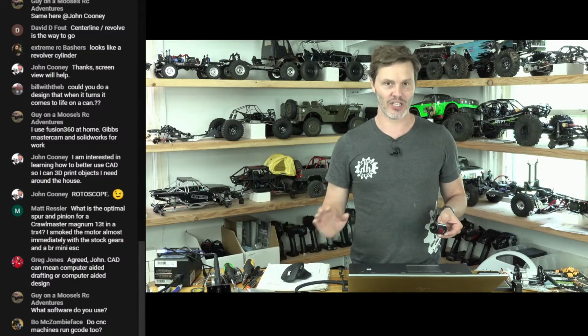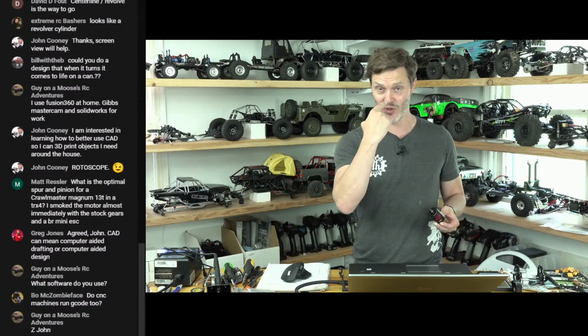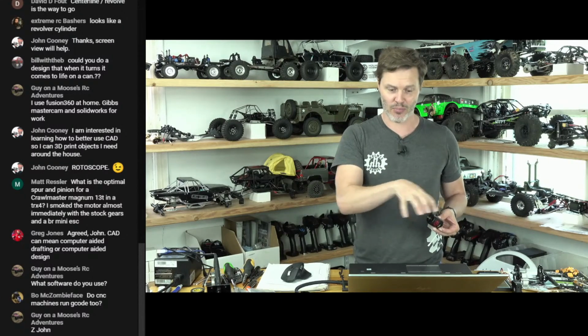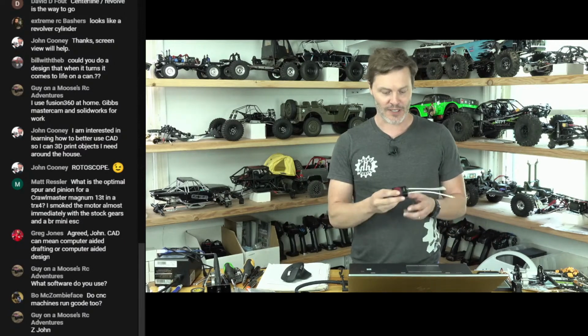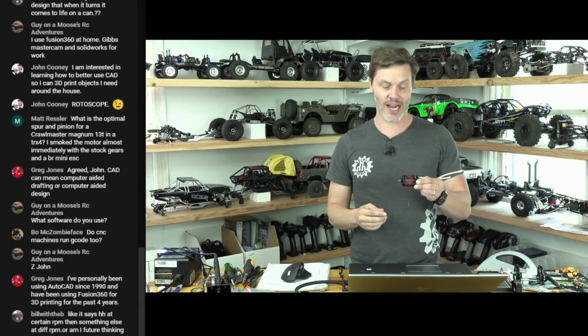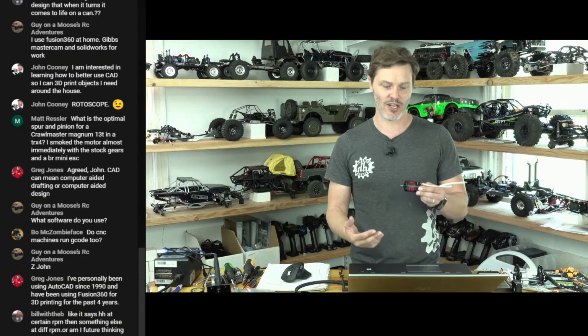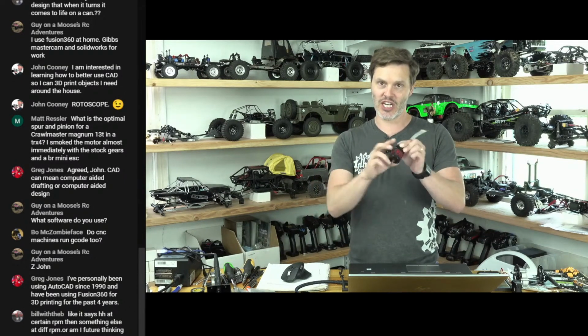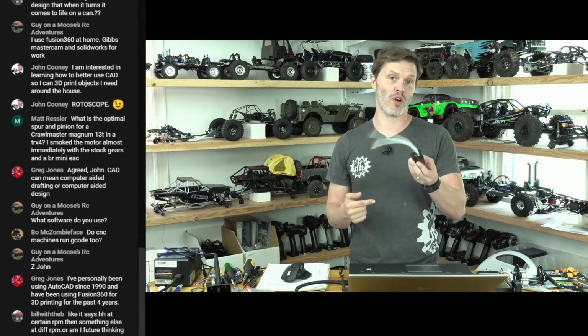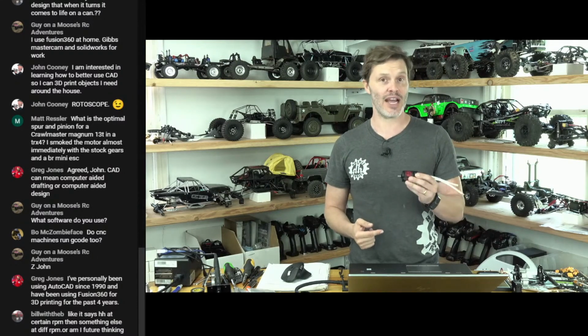If you're going to 3D print, you always want the Z facing at you, as if you're looking down on the print as it's being printed. That way you don't have to flip it when it gets into your printing software. But the way I'm going to think about this design when I start is that this is going to be a machined object on one side or another, so I need to be careful how it's designed.